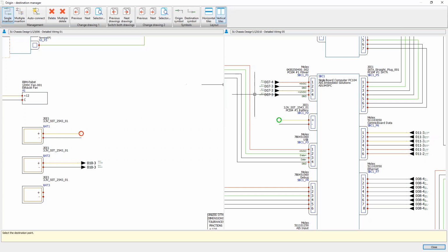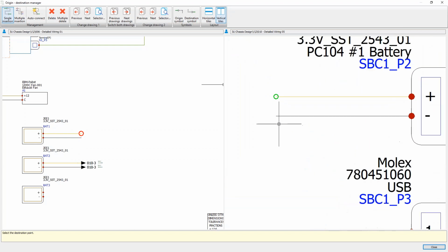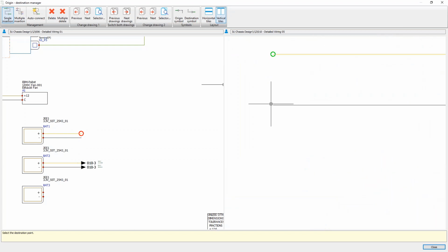So select the orange wire, and if you notice, it will not let me select the black wire. Again, it's a nice little design rule check. If you've ever been involved with trying to get a schematic done extremely fast, I've been there where it's like, hey, it's Friday, we need this done by the end of the day. Oh, thanks for the heads up. And now you're just trying to draw it all out and get it out the door. Well, if you have your wire styles set up, this will help alleviate that pain, so that 2 weeks from now, you won't find that there was something cross-connected because you were in a rush to get that schematic done, which is a nice little touch.